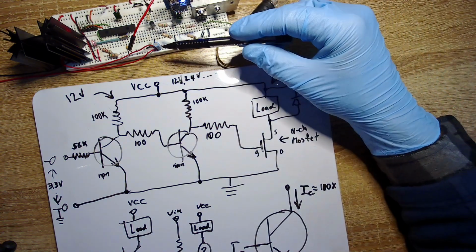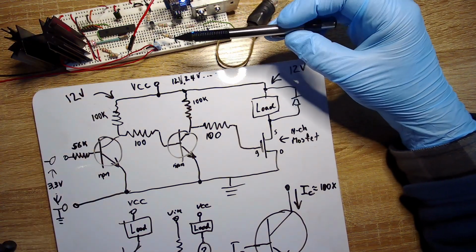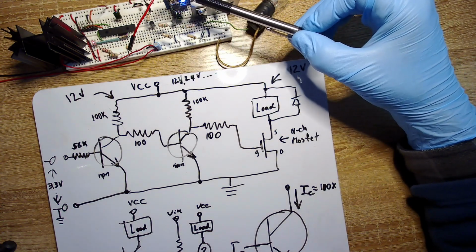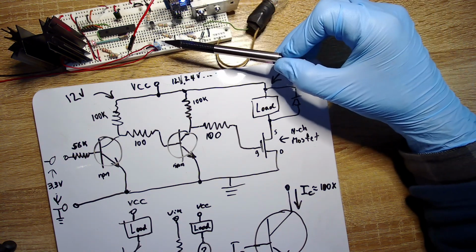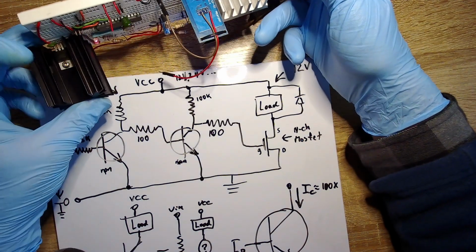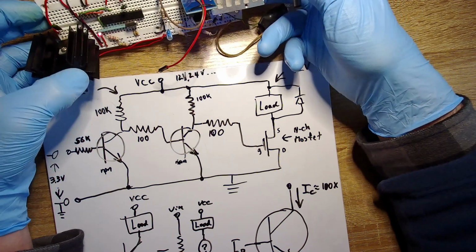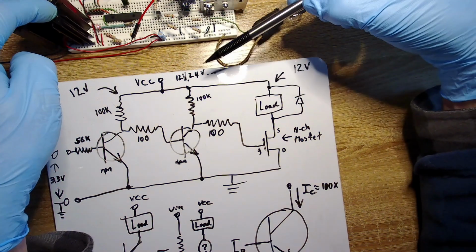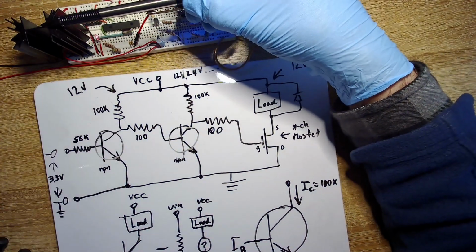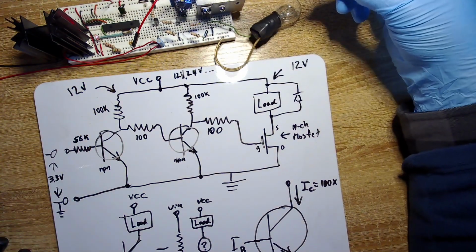You'll see some capacitors and things on this circuit board, which are mainly for the voltage regulator, because what you'll find is when you start putting interesting things like computers on a regulated supply... this is a 5-volt regulator, right? It's over here on the left side. Basically what I'm doing here is taking 12 volts, bringing it down to 5, and then bringing it down to 3 point something, right? So I've got these 3 tiers of voltages.